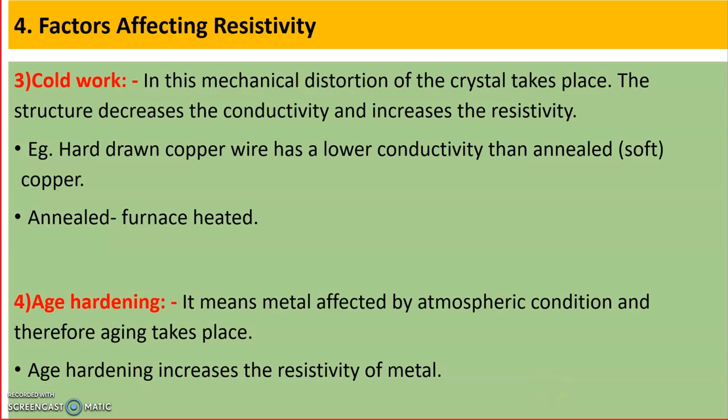So factors affecting resistivity are temperature, alloying, and third is cold work. In this, mechanical distortion of the crystal structure takes place, which decreases the conductivity and increases the resistivity. Now see, if you are considering copper or any material, how it is made, how it is constructed, whether it is hard drawn or cold drawn. Sometimes steel annealing is done, heating is done, so that will change the resistivity.